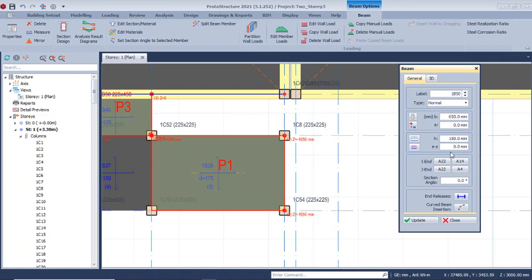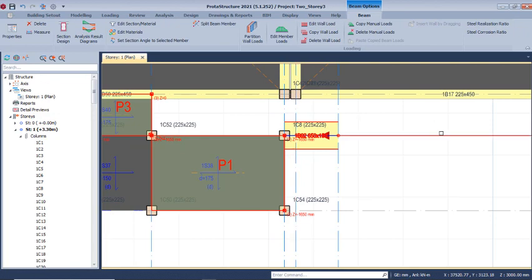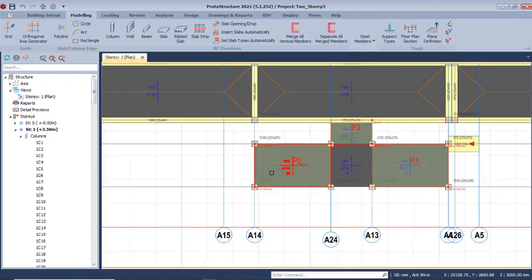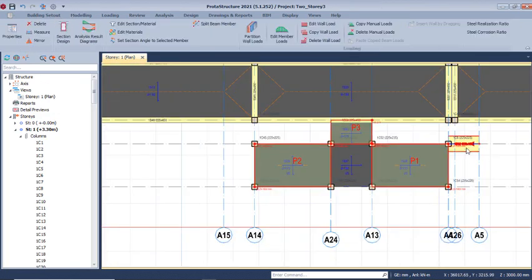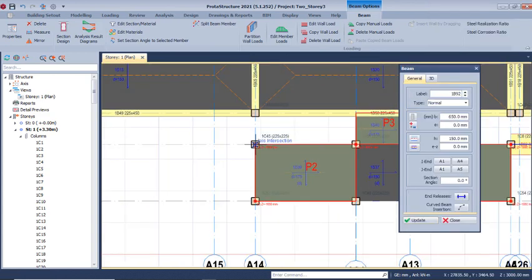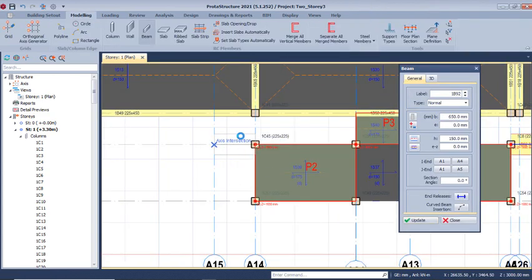So this is a kind of concealed cantilever beam. So we are going to pick it from the point and then take it over to the point, and then we'll have something like this. This is a concealed cantilever beam. All right, so understand that we close these provisions now. Now we want to place the slab. The same thing on this side, because we have slab on both sides. Concealed cantilever beam over here. So we place it here. Concealed cantilever beams as well.